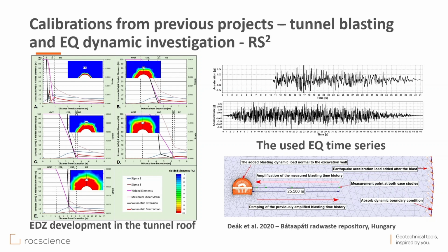You have to mention also that the damping of the soils and rocks is independent of the loading frequency. By contrast, the Rayleigh damping formulation is frequency dependent and adequate to solve numerical damping. Use of Rayleigh damping in the numerical models allows the user to define the damping ratio for two threshold frequencies. Between them the model has a damping ratio lower than the specified damping ratios, and frequencies outside this range are damped more heavily. Numerous variations of the two frequencies and damping ratios were modeled, and the most appropriate result was set to the measured one, in our case, of course.